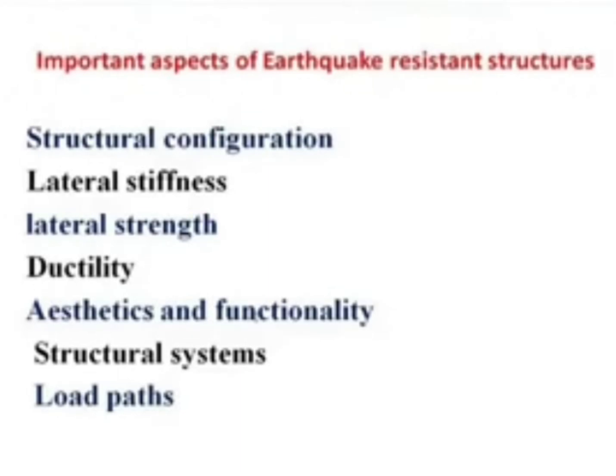Lateral strength. Stiffness is something, strength is something. Strength again is related to the material. Then ductility. Very, very important. The structure will not collapse immediately. Or even if it undergoes huge deformation, huge cracking, still, by seismic retrofitting, you can reuse this structure again.